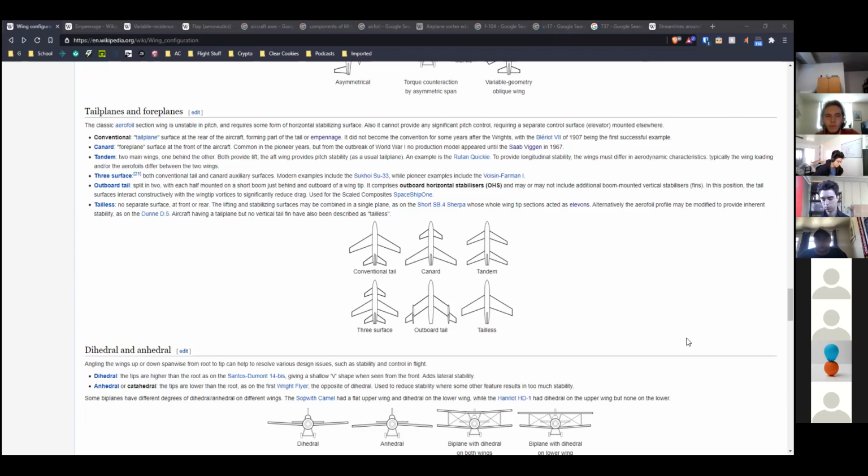And because we have a CNC foam cutter, you basically have to trace equal points of the root section and the tip section at different rates, so that the wire is always on the surface of the wing you're trying to cut out without ever cutting into it. So it's harder to make out of foam, but I feel like we could probably try it.